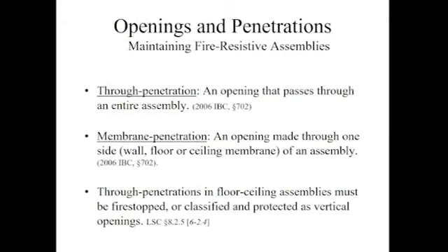It won't last if you have holes. I mean, you get a hole through the wall, there's no doubt fire and smoke is going to get through it. That assembly will not last through a fire, it'll fail. So both the IBC and NFPA 101 Life Safety Code require the protection of openings through the assemblies.